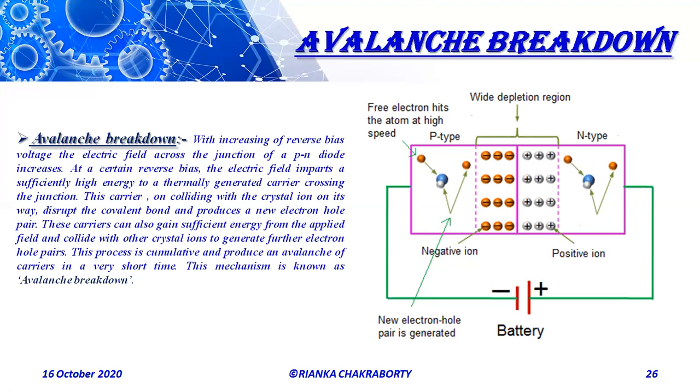If the reverse bias voltage applied to the avalanche diode is further increased, the minority carriers will gain a large amount of energy and accelerate to greater velocity. The free electrons moving at high speed will collide with the atoms and transfer their energy to the valence electron. The valence electrons, which gain enough energy from the high-speed electrons, will be detached from the parent atom and become free electrons. These free electrons are again accelerated.